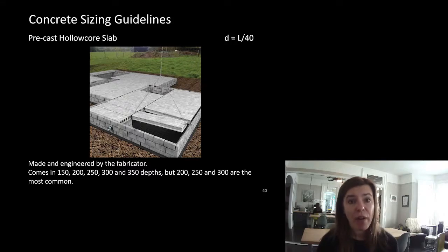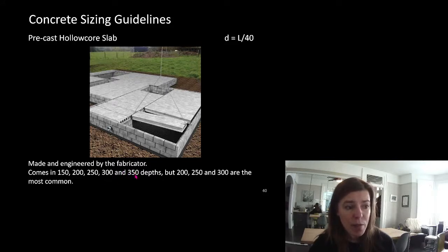So you have to be very aware of that in your drawing, that you might get a few millimeters of play out of that. I would always recommend drawing the deeper one. I would maybe call it the 350, but I would maybe draw the 356 just to be careful.